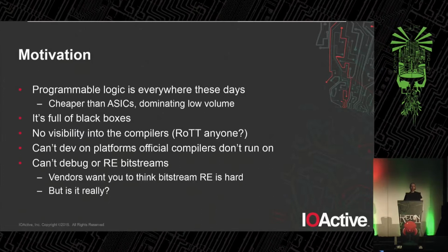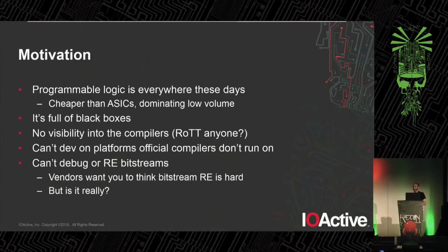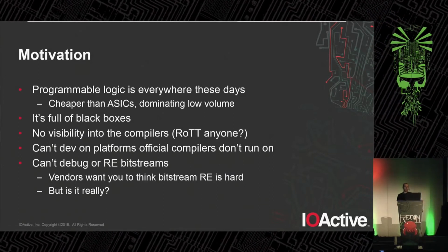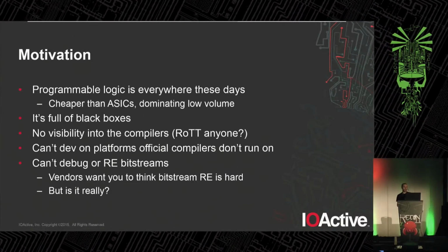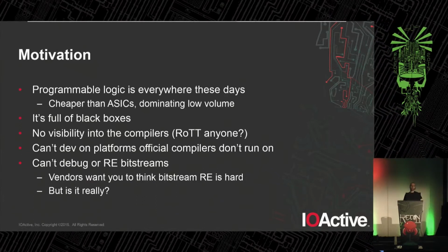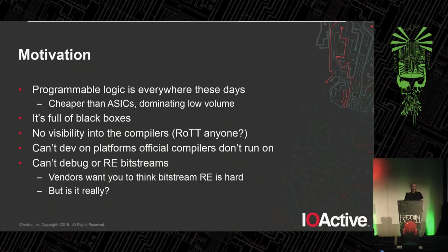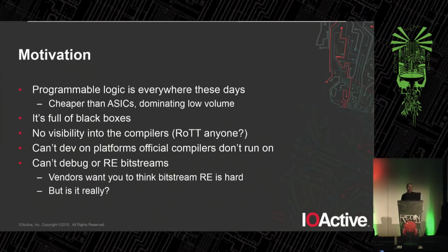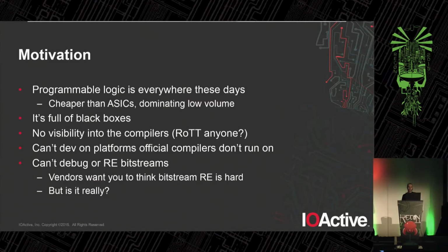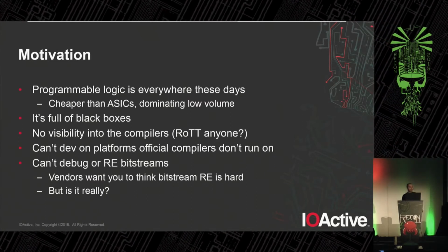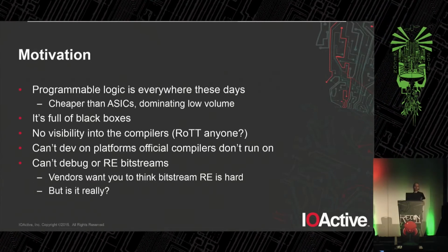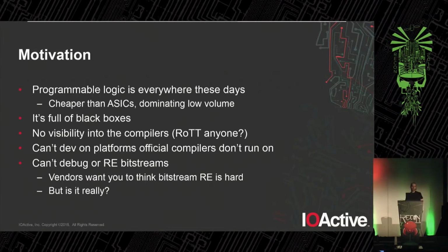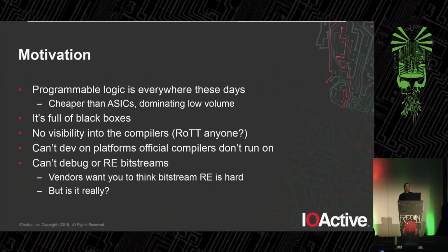As far as what we're actually trying to do and why, programmable logic is really everywhere these days. You may not know it, but a lot of, especially high-end networking, AV, all sorts of stuff has programmable logic in it. Because ASICs these days, the tape-out costs are so high, especially for leading-edge process nodes, it usually is not actually cost-effective to make custom silicon unless you're making a huge number of them, like for a smartphone or something. For anything else, you're probably better off running on an FPGA.